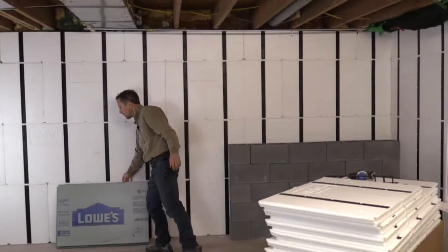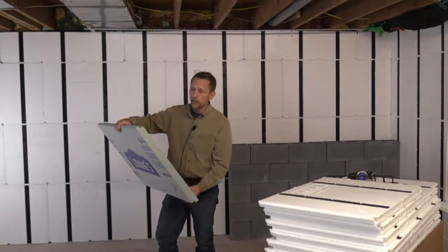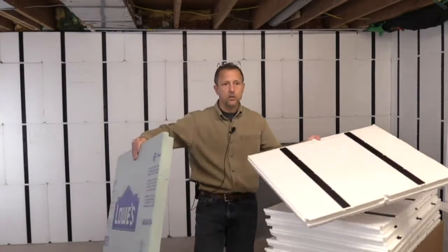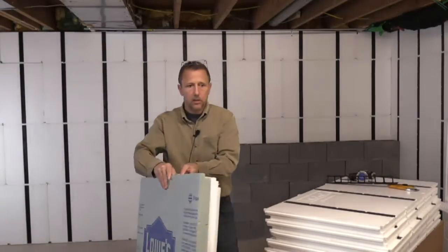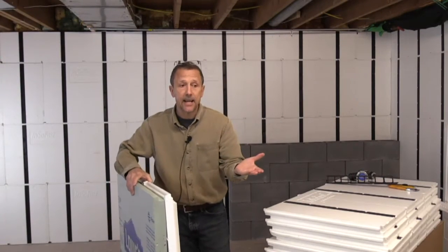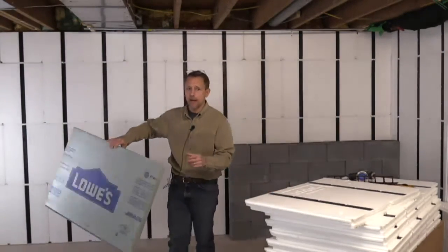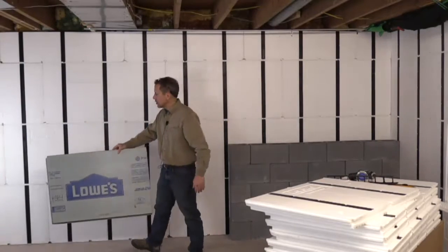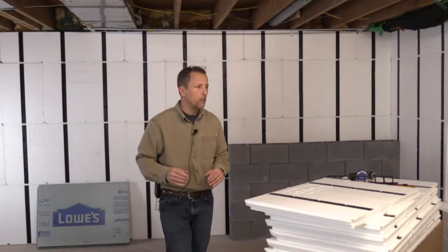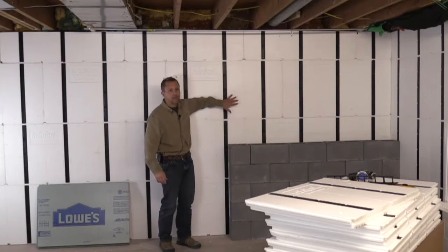This would be a regular foam board that you can get almost anywhere. This would be an R10 for 2 inches. So if you were to put these two together, you would get an R 18.5. So that's what we're going to show you today, how to achieve that R 18.5 with either 2-inch foam or 1-inch foam. I'm going to show you both methods, but we're going to start off by actually doing this.